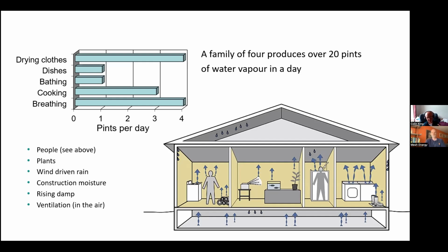And if you ever get involved in designing buildings, a lot of the time you'll find that this is just dumped on the M&E package. I will get them to sort the ventilation out. But it rarely comes with a proper ventilation strategy for the design, occupancy, and potential use of that building, so that moisture as we go forward doesn't become an issue. And it's really, really important.